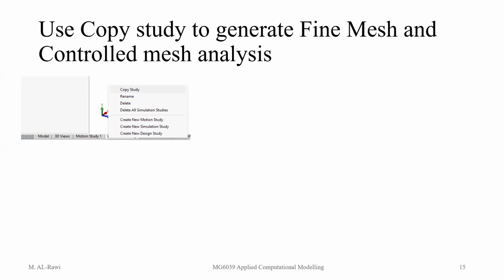All right. So when you copy the study, you name it. You do it twice. First one, call it coarse mesh. Okay. And then do the copy again and call it fine mesh. So we're creating two studies from the default one.